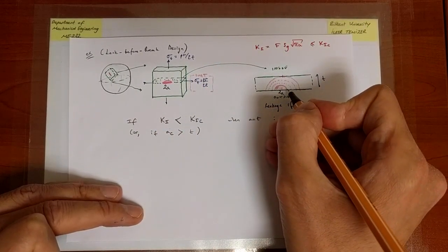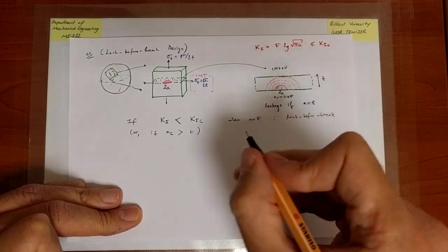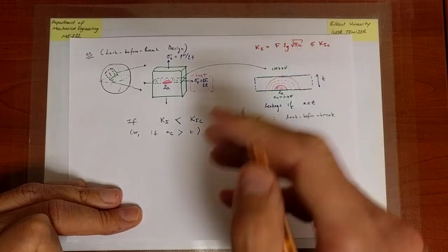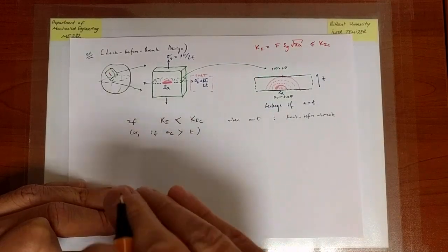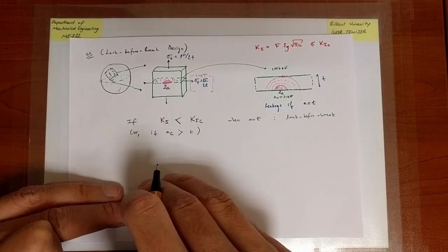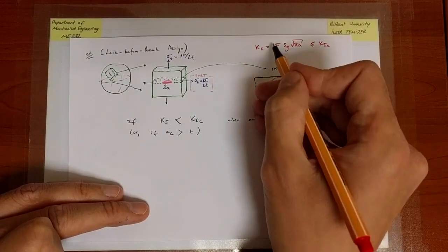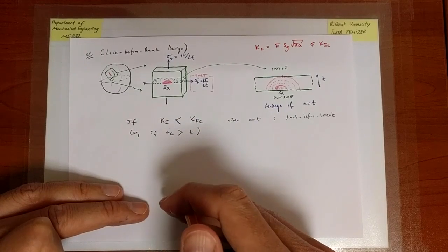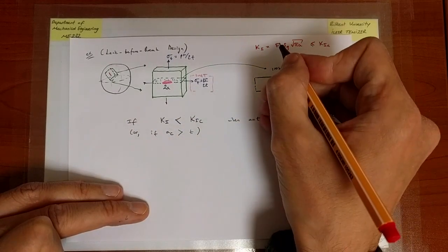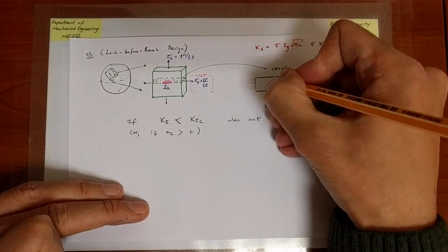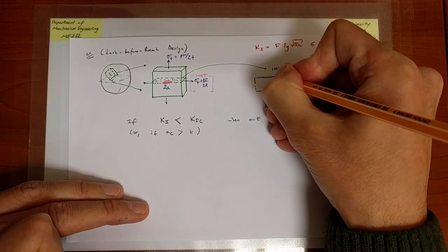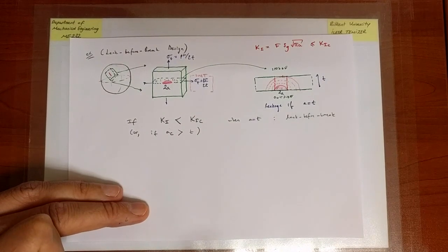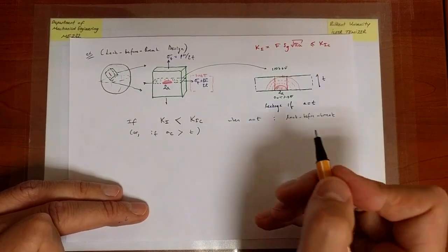It's a penny-shaped crack. But what we are going to do is we are going to assume at any stage, although this is our criterion, to apply at least in our analysis. So in general, you don't have to do this. In general, there is a form factor that applies to this scenario. But what I'm going to do is at any stage, I am going to calculate the value of F as if the crack was a through thickness crack. Now, this is not physical. It's just an idealization for the purpose of analysis. If it were physical, it would leak already.